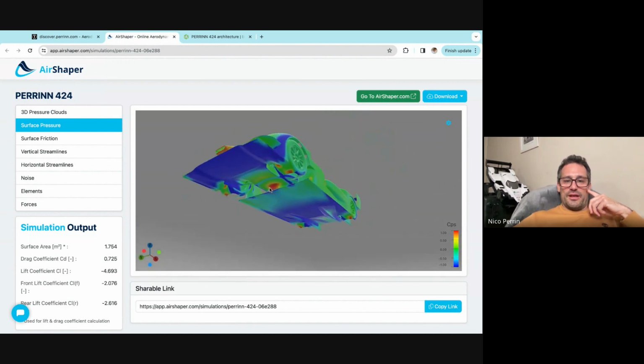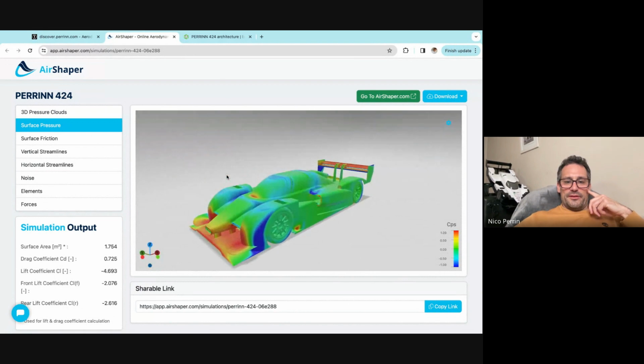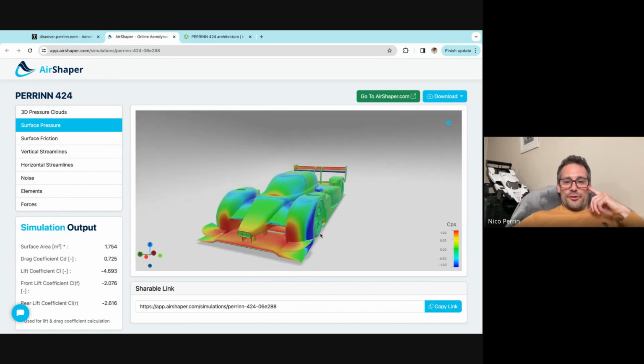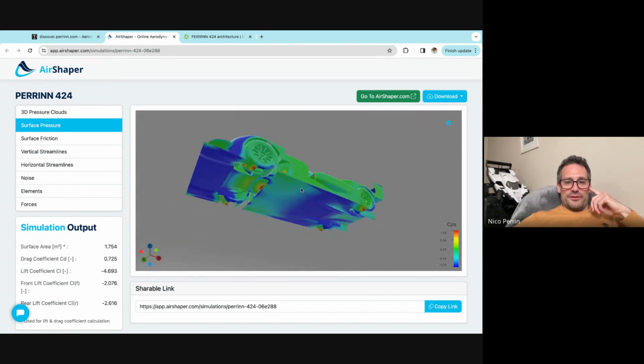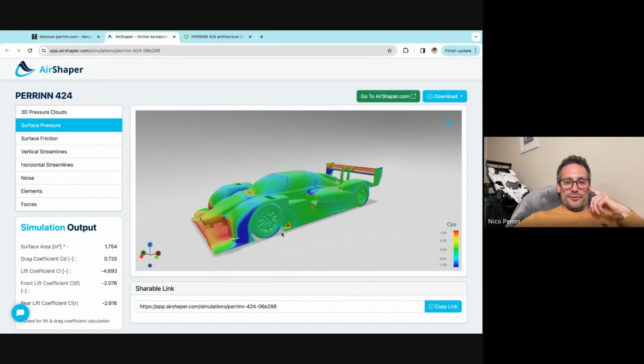And then the front of the car, it's all about working that front wing as hard as you can. So first of all, I've explained that less volume on the wheel arch, we create these red areas, which is creating downforce through pushing down on the front wing. But as always, it's all about what's happening under. And you see the blue, the integration of the blue is actually more important than the red over.